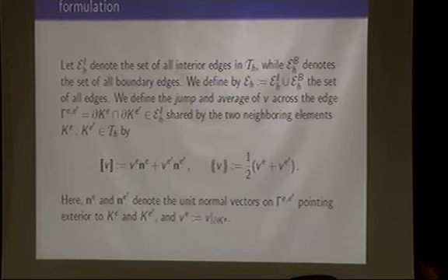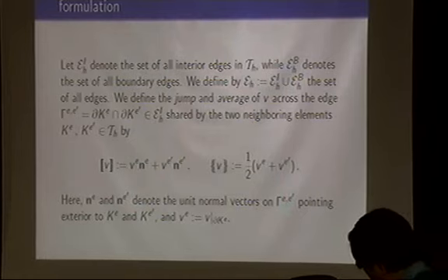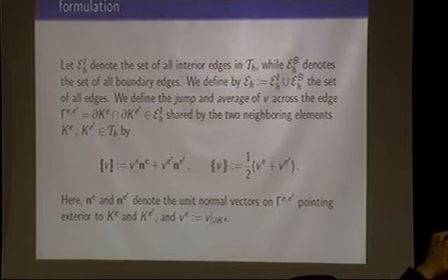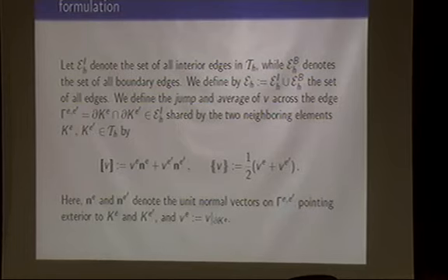So the second one here is the numerical scheme. You can have a stable analytical scheme, and you also have to have a numerical scheme which verifies stability, right? So I usually use 3 different methods: the finite difference method and the finite element method. You have a newer finite element method, that is the discontinuous Galerkin. If you have a discontinuous Galerkin, you have in the end the block structures of the matrix. You have here an equation, but if you want to calculate with the computer, you have to have very big matrices. If you have a 3D domain and time, you have very huge matrices. There is a big problem, right?